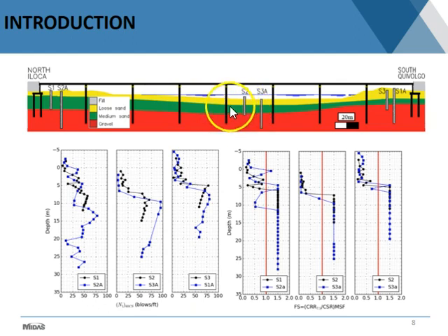And of course, that's what we found. We found that the yellow one that is marked here is the material that is susceptible to liquefaction. For this analysis, we used a PGA of 0.4 g, which is the closest station measured for this area. I mean, 0.4 g was rather usual for the earthquake we had 7 years ago.